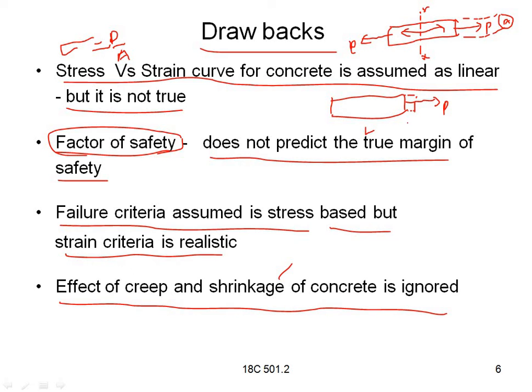This portion is determined as delta L. So up to L, it is known as the actual length. When the change occurred, delta L is known as the change in length. So here the strain is described as change in length by original length. So this is also called deformation or displacement of material that results from an applied stress, and it is called strain.